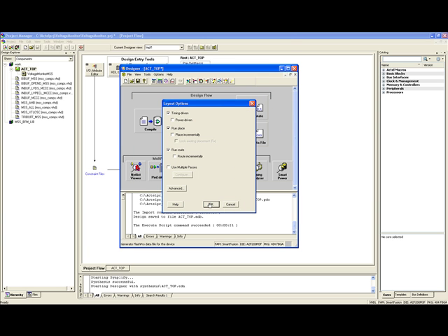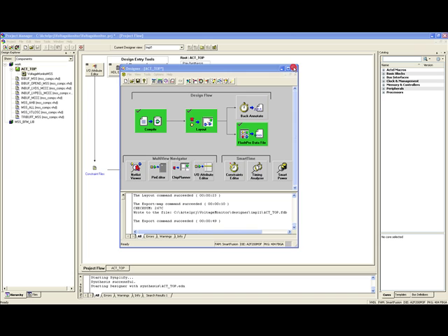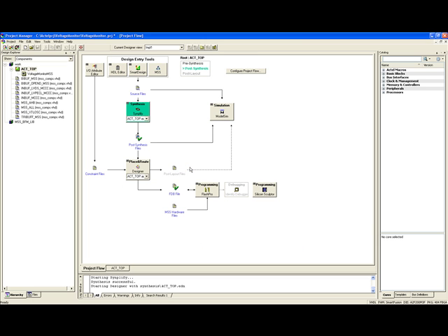With the timing-driven mode selected, layout will run several times to achieve the best timing, so it will take a few seconds to complete the process. When the Compile, Layout, and FlashPro Data file buttons are green, the process is complete. Close Designer and click Yes to save the file.